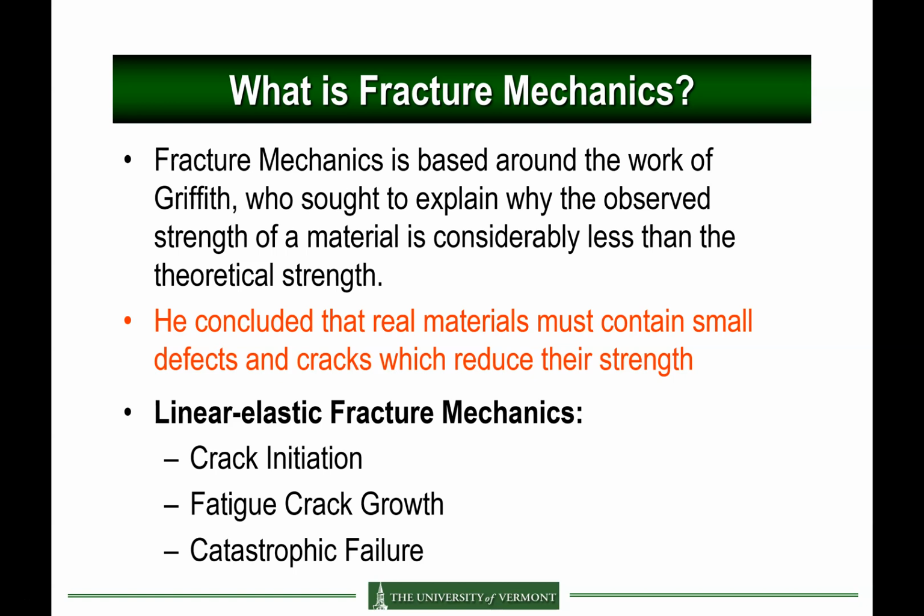So Griffith's fracture criterion is essentially based on energy. But fracture mechanics is focused on stress intensity at crack tips. So when we talk about fracture mechanics, we discuss three stages in the propagation of cracks, and this falls under what we call linear elastic fracture mechanics, where we assume that the crack is embedded into a purely elastic material.